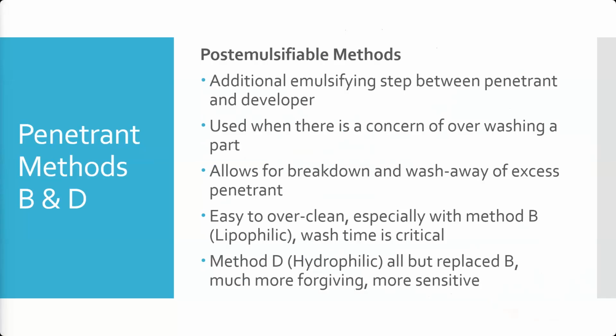So anyways, it is used to dissolve food grease and that kind of thing and allows water to wash that away. That's the same thing that's happening here with these method B and D penetrants: after the penetrant is applied, we have to use an emulsifier to allow the water to remove it. With method A, the water washable, the emulsifier is actually in the penetrant already. So that's why these are called post-emulsifiables. You put the emulsifier on after the dwell time, and so you have that initial emulsifying step.